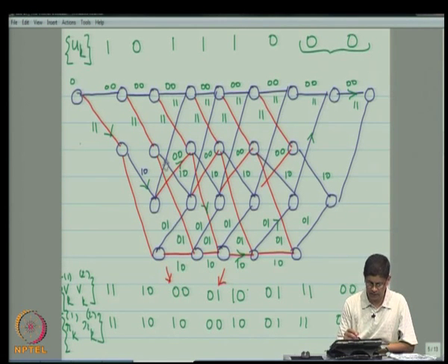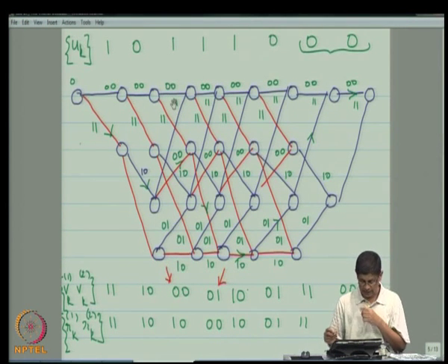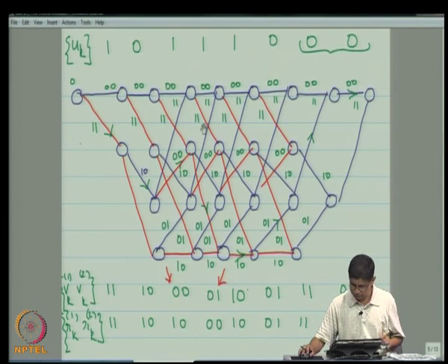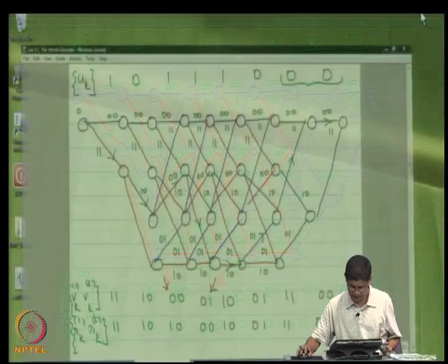The path has length 3, okay, and the number of message symbols that are 1 is 1. So, this would correspond to an L cubed I, and the corresponding output sequence has Hamming weight 2 plus 1 plus 2, 5. So, it would correspond to an L cubed I D5 term. Okay, so that gives you some idea, I hope.